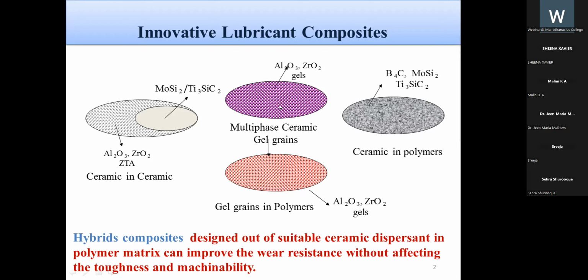Actually, a lubricant is a substance that is introduced to reduce the friction between moving surfaces. Usually, we are using liquid lubricants. Liquid lubricants dramatically decrease the coefficient of friction. Today, in our daily life, we are dealing with various machines. Frictional loss is one of the important losses in machines. But liquid lubricants are impossible in certain applications in which ceramic parts operate under conditions of high temperature, vacuum, or corrosive environment.